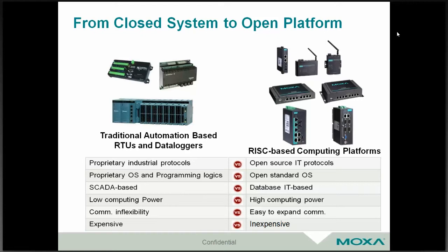On the OS side, those RTUs and PLCs have a proprietary OS and proprietary programming logic. Although IEC 61131 is the primary language used on RTUs and PLCs, different vendors have different ways of programming it, and it requires a few days of training before you can actually start the programming.